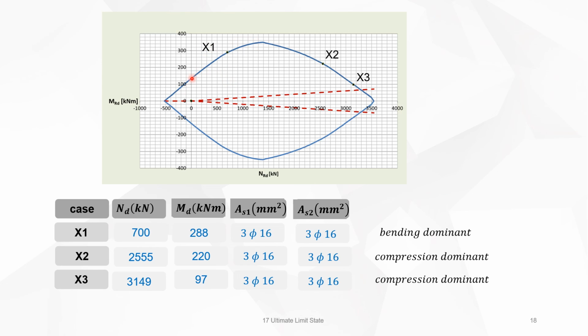You will also see that this curve is going up until it reaches a maximum, and then it's going down. Well, this portion is dominated by bending. It's bending dominated. When we go a little bit further, this portion here, it's compression dominated. So you can see on the graph, if you are over the hill, then you tend to go to the compression dominant, so you tend to go to the 2B domain. This is domain 3, this is 2B, and this is domain 2A.